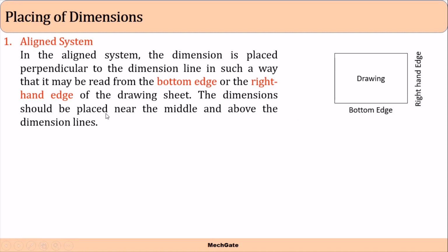The dimension should be placed near the middle and above the dimension line. So the dimension should be placed near the middle of the dimension line and above the dimension line. Here we will not cut our dimension line to place our dimension.